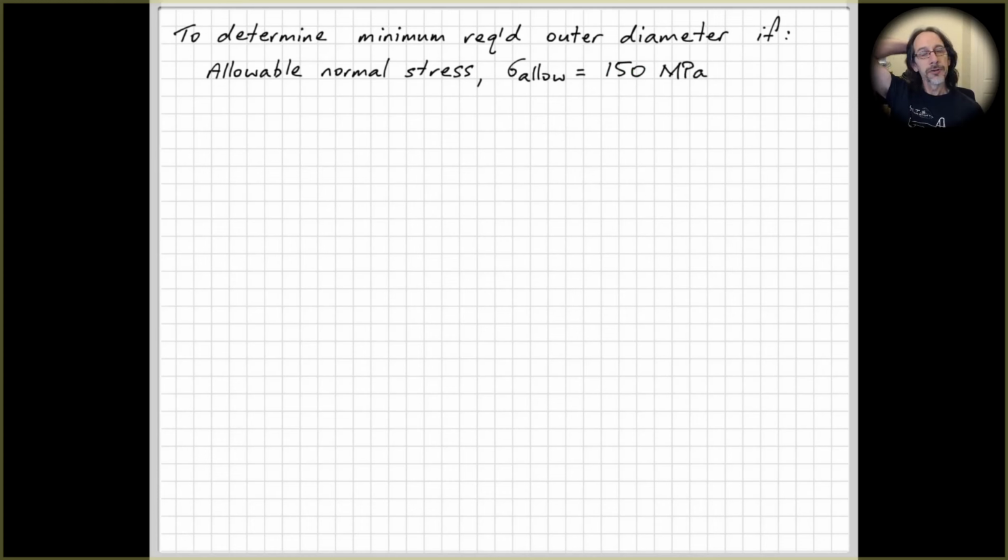Because this is a shaft, normally I don't really like doing this simple approach to design for a shaft that's rotating. Because really, if it's a rotating shaft in bending, then you really should be doing a fatigue analysis. But just as a demonstration and just to do something simple to start with, we've turned this analysis problem into a simple design problem.